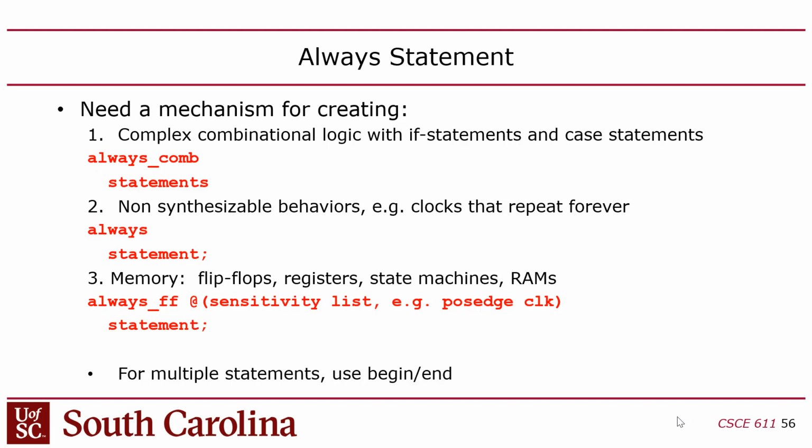Okay, so now one thing that we have in SystemVerilog that helps a little bit is that SystemVerilog introduced variations of the always. So we have always_comb, and we have always_ff, flip-flop, and there's also a couple other ones.